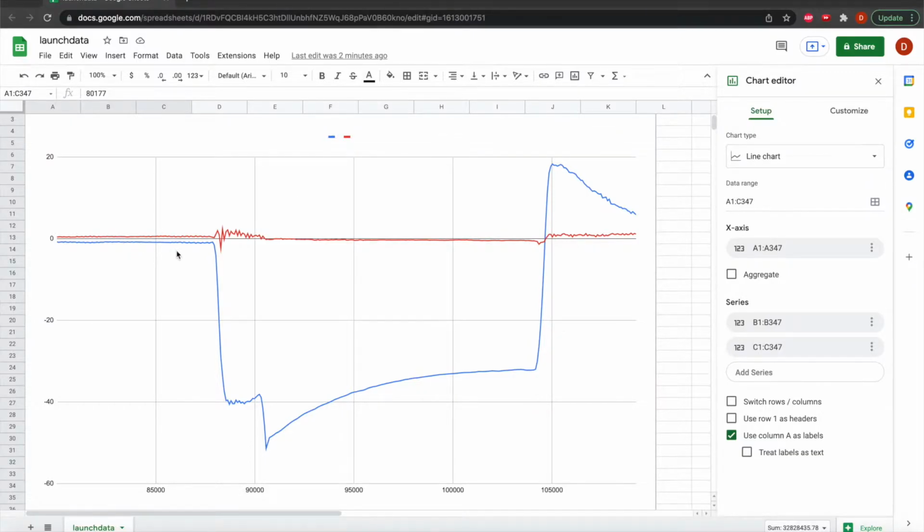So here we can see that the rocket launches right here, it ignites, and the pitch angle drops dramatically to about negative 55 degrees, and we can see from there it tries to correct itself. As we can see it increasing, it tries to get to that 0 degree line, but it actually doesn't. But this tells us that the thrust vector control is working, it's just not as effective. And then after that the rocket engine stops firing, it goes all the way back up to about positive 20 degrees and finishes off. And so this tells us that the thrust vector control system on the pitch axis needs a lot more improvement.